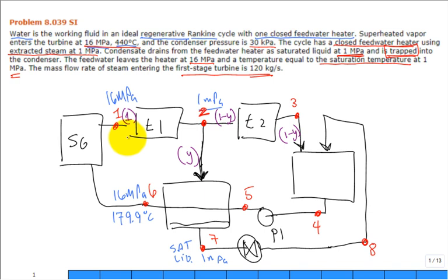All right. Now, let's go down here. If it's Y on the shell side of this, then it's Y coming out as saturated liquid, going through the steam trap, which is then Y coming over here from state 8 and feeding the condenser. That's why I kind of put them both at the top, both feeding at the top of the condenser. So what is it at 4, the saturated liquid coming out?